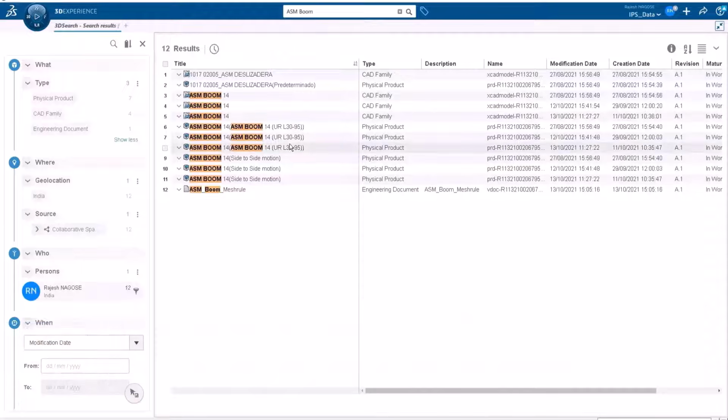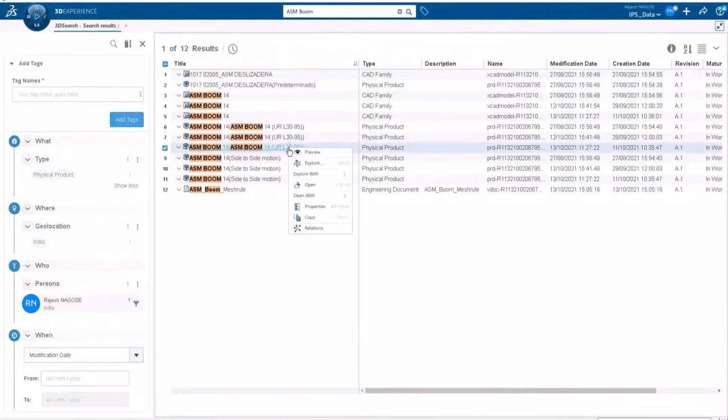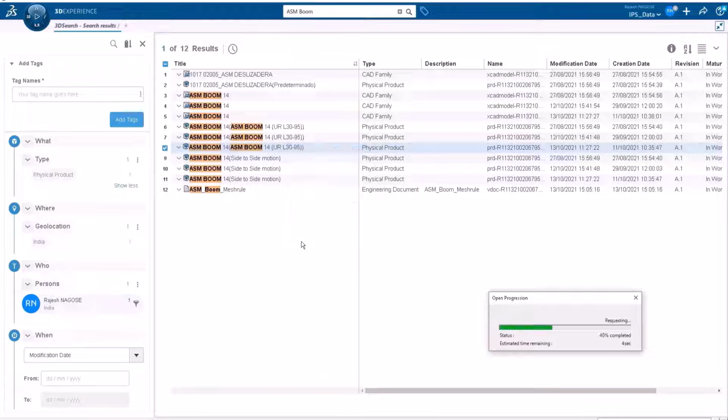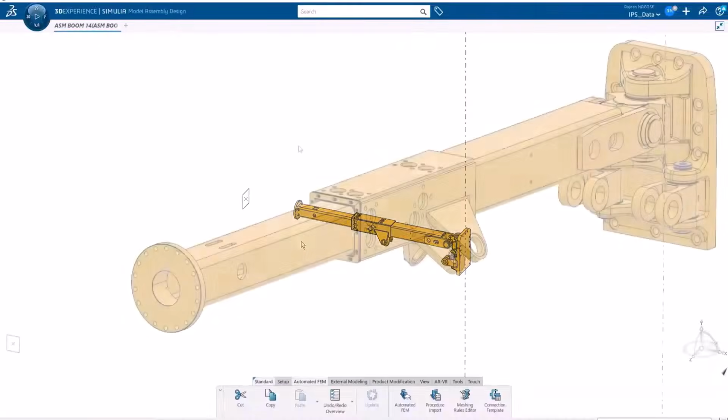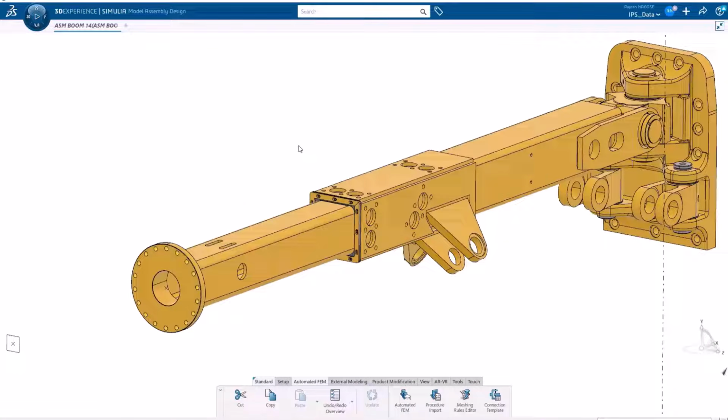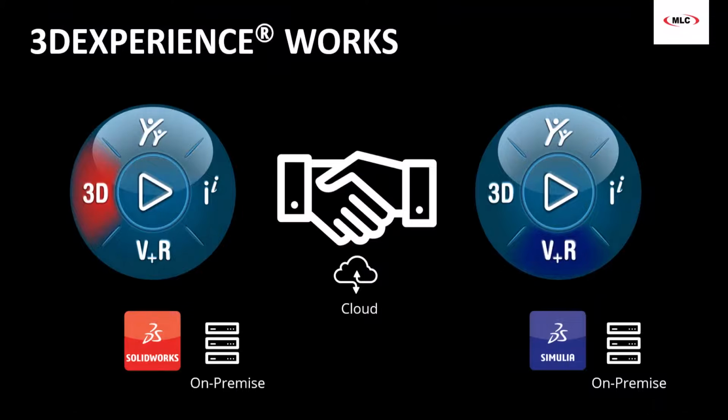so it's preparing it to be opened up on the Simulia side. Now this interface you're seeing right here is the locally installed simulation interface. It's the native app for Simulia. We're simply opening up that same SOLIDWORKS file now over here, ready to start a simulation. That's as hard as it is to make a parametric link between SOLIDWORKS and very advanced simulation software. Right-click in the task pane and save it up. All right, that's the easy part.